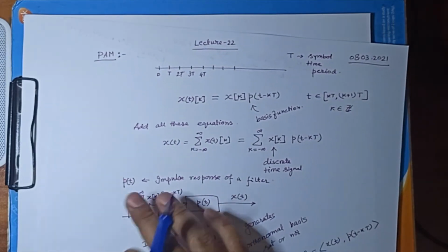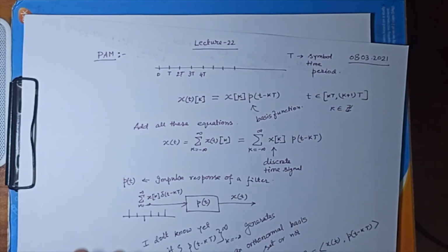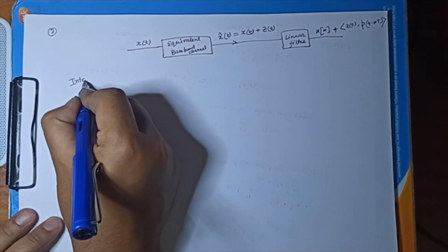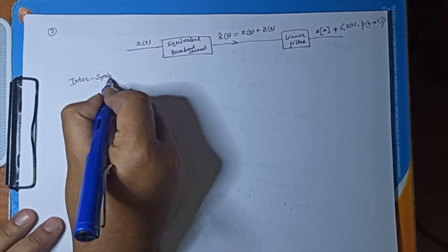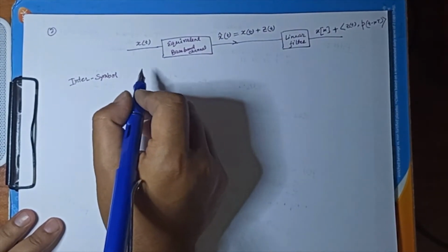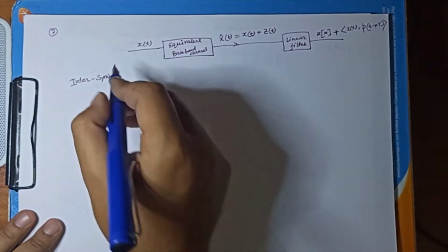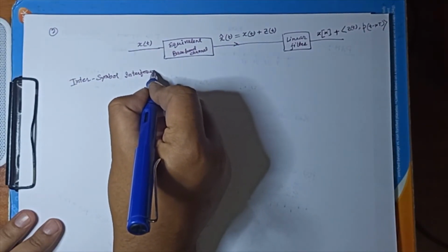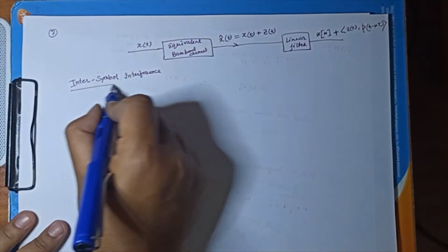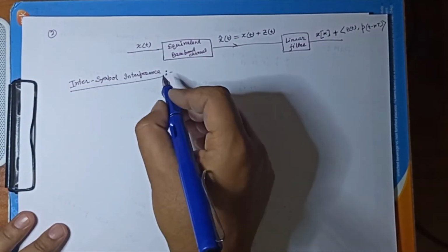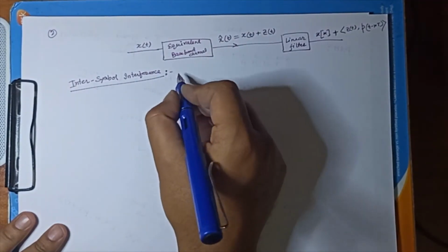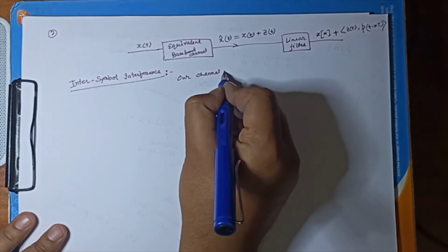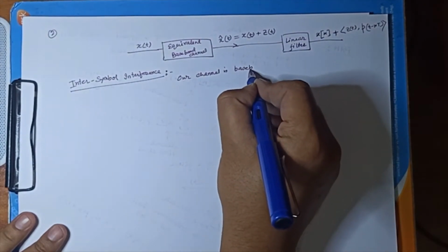There is another thing which we will introduce today, which is called inter-symbol interference. This is one problem which is essentially a signaling problem. Even if there is no noise, this is possible. And why is this possible? Because our channel is a strictly baseband, band limited channel.